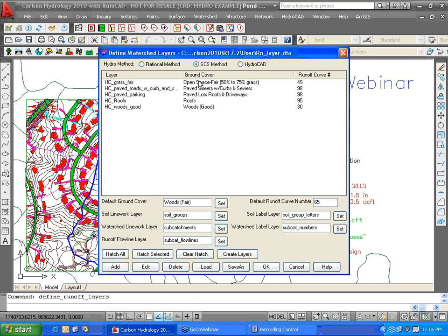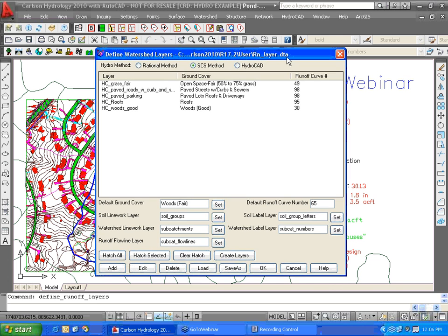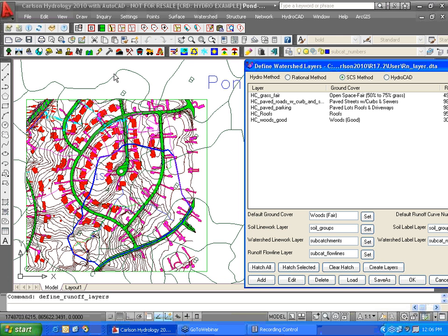And then in addition, your eyes need to go down to this lower zone and note some of these layers of the automation. For example, we can have soils. If I move this out, I have soil boundaries with soil types designated by A, B, C, and D, simple letters within boundaries that don't have to be closed polylines.